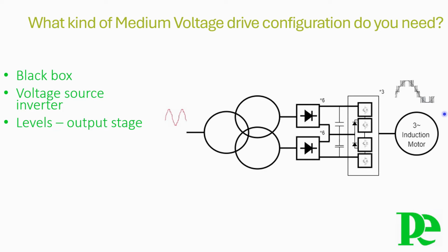Notice that the phase-to-phase output voltage of the three-level inverter is made out of 5 steps and is already looking much better than the two-level output voltage. Some manufacturers also offer a 5-level inverter, but it must be noted that if the 3 or 5-level inverters are to drive a standard motor that is not inverter duty, these inverters will require a sine wave output filter in order to reduce the common mode voltage and the voltage stress on the motor. These supplemental output filters can be of a significant cost and might also introduce performance restrictions on the power drive system.